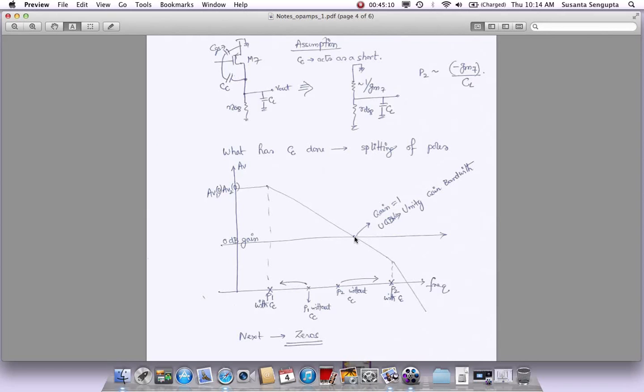Typically, for all these op amps, if you know what your unity gain bandwidth needs to be, let's say 100 megahertz, we'll try to make sure that the phase margin is roughly 60 degrees or better, so that it is stable, and over temperature and different process corners we are not going to lose that 60-degree number too much. Maybe it'll go to 50 degrees or 40 degrees, but not too much, because the lower the phase margin, the closer it's getting to being oscillatory.